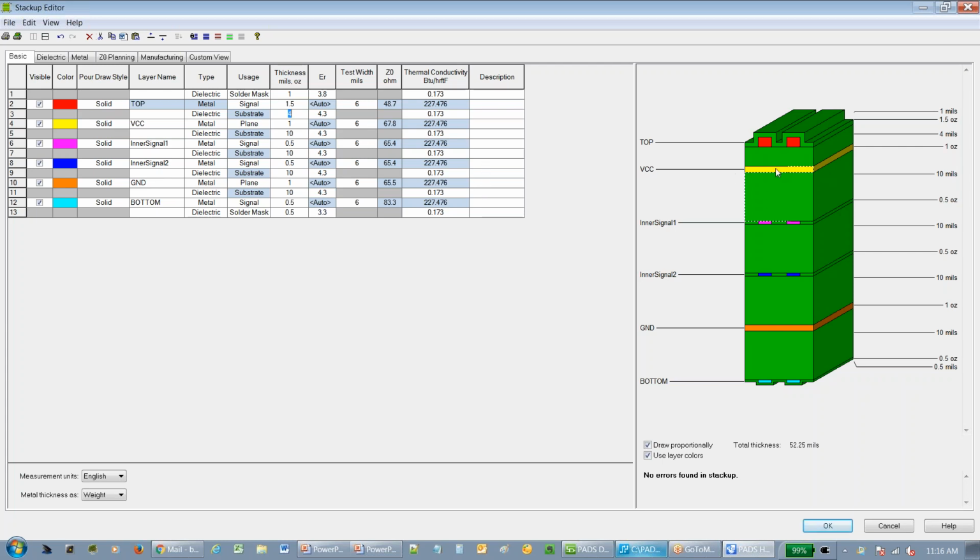So people doing really high speed design actually use the power planes as a capacitor, because it increases their frequency range, because capacitors that you put on a design can only handle so much. And you need capacitance levels that the devices you can put on the board just can't achieve. Plus you start running into inductance issues. There's all kinds of other weird things that start to happen when signals start getting really fast. But for most of the stuff I'm talking about here and the average design a person's doing, play around with things like putting the planes maybe closer together, which can help with your power supply distribution network in your board.